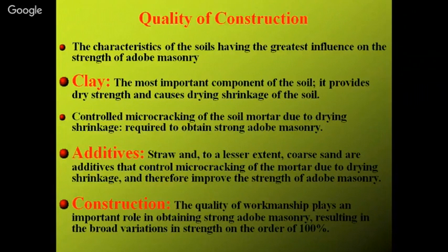For strengthening your mud house, you can add straw, or you can apply a non-erodible mud plaster on your wall. There are different kinds of other adhesives which you can add to the mud and make your house earthquake resistant.